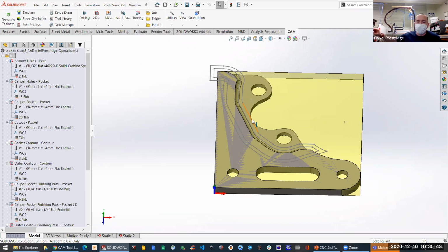So I choose to use something that doesn't interact with the liquids, so I can repeatedly run the same operations and then cut the top part off and do it again. So this is a little bit thick. I make sure that I can run a bunch of 0.5 millimeter increments down until it's basically a throwaway, and you would either practice on it a little bit and then replace it with something else, or you can go with the sturdier fixture method.